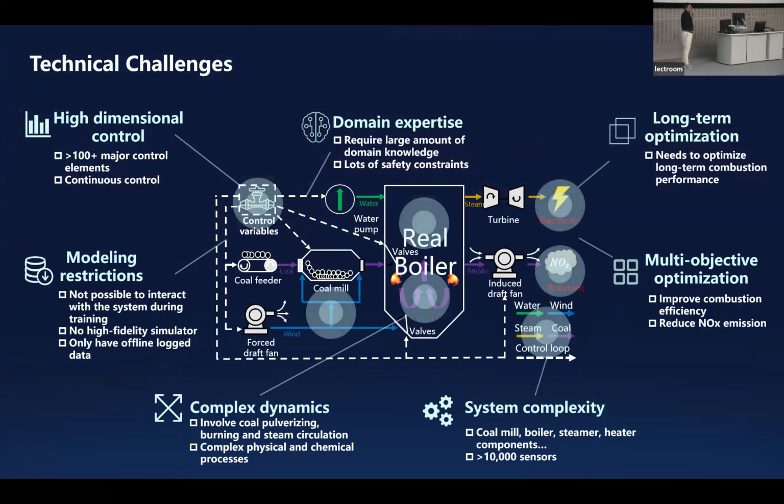It's like you generate electricity through a thermal power generating unit, and the process is like this. You have the coal, and you crush it and pulverize it into tiny ashes, and then you blow that with wind into a massive boiler, which may have a height of a 10-story building. Then you need to inject coal and air through maybe 20 to 48 different locations, and ensure they are poured together and form a huge fireball in the center of the boiler. You need to carefully control the water, the wind, and the coal, and everything needs to be just right to maximize the combustion efficiency.